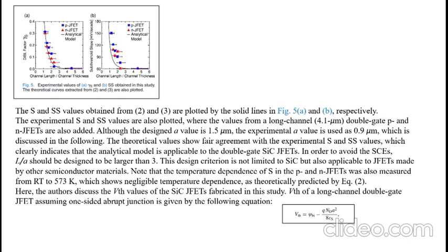The theoretical value agrees with the experimental S and SS values, which clearly indicates that the analytical model is applicable to the double gate SiC JFET. L divided by a should be designed to be larger than 3. This design rule is not limited to SiC but is also applicable to JFETs made of other semiconductor materials.